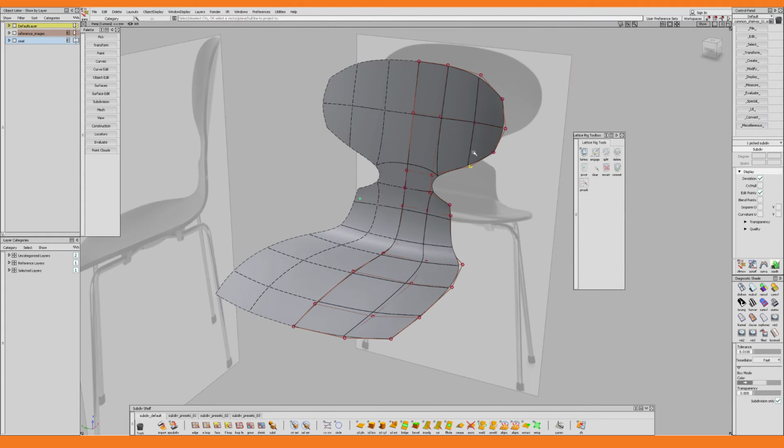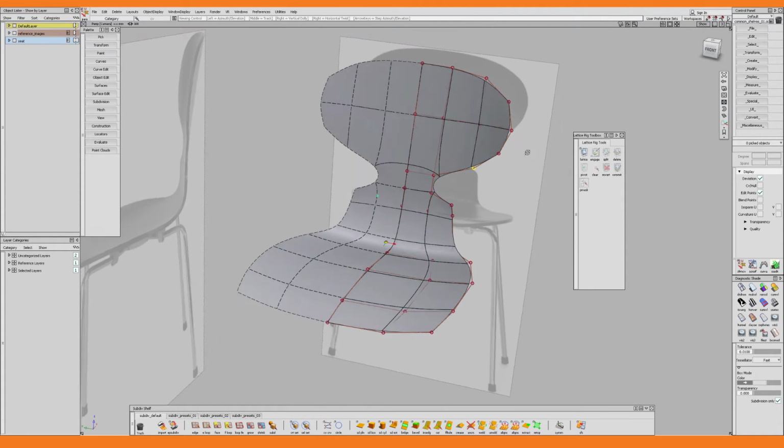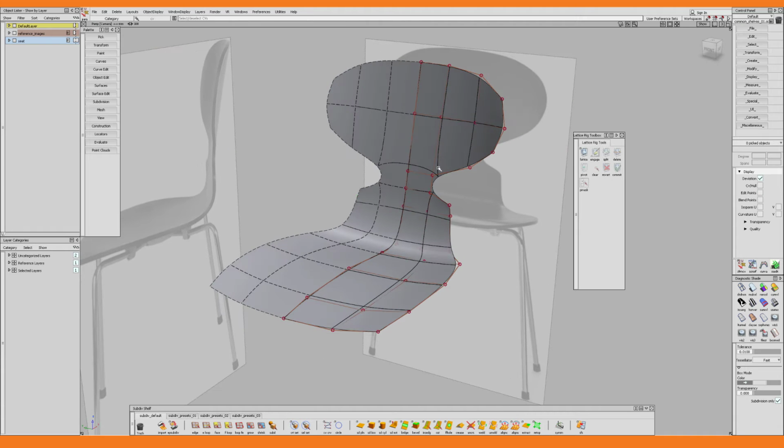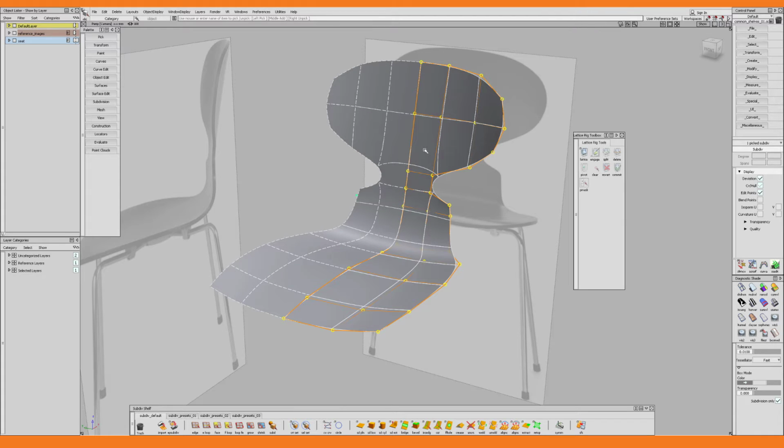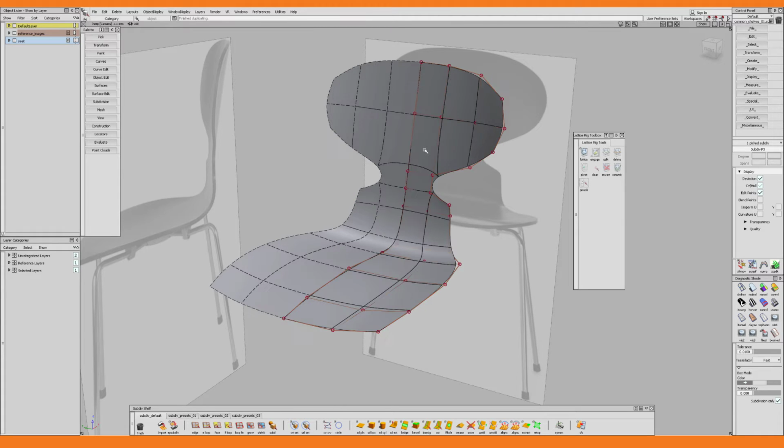And here you see me using it once again to make this tiny tweak to that one vertex. I'm sure that will make a huge difference in the end. Now I want to add some thickness to the seat by extruding all the faces. But before I do that, I need to make a duplicate of our subdivision object, and you will see why in just a minute. So I select it, and then I use Ctrl+C, Ctrl+V to make a copy, and I